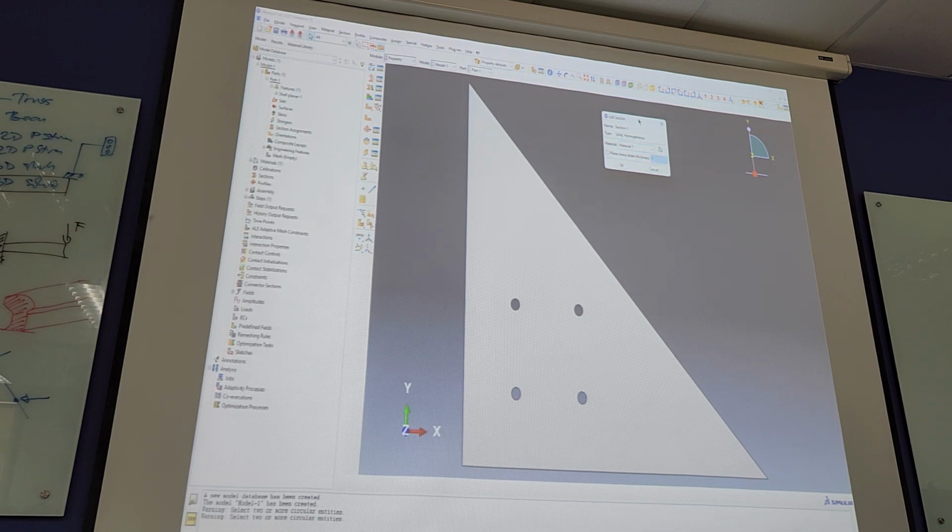Yeah, so it's a solid, and for all solids it's the same prompt box. Now, this becomes relevant to you if you are dealing with plane stress and plane strain. This is where you are specifying thickness. If you do not specify thickness, Abaqus assumes a default value.